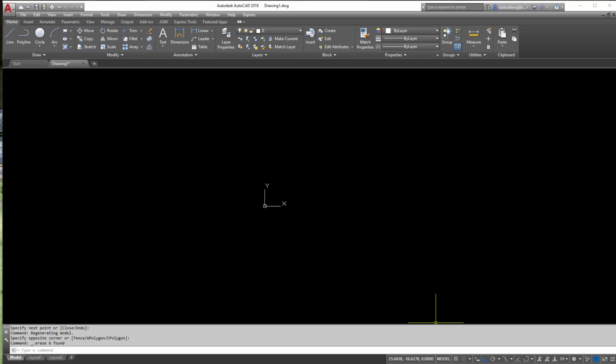It seems to be the easiest way to draft, and that was using ortho, but of course you can always do the same thing using your polar as well. So you just lock yourself in, go 6, and then again 6, and you can draw this however you want, maybe go 10 this time, and then hit CL for close to close back, whatever you want to do. But those are the few different ways you can draw lines using AutoCAD.